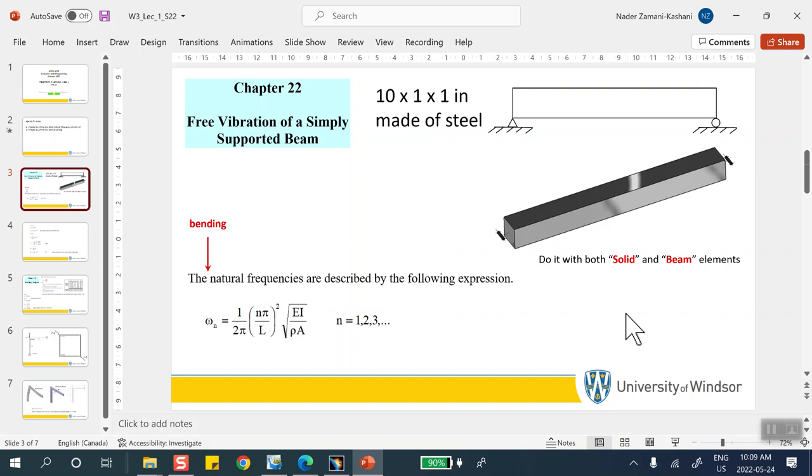this is a fact, avoid using planes of symmetry of the structure when you're doing natural frequency calculation. Because if you said this structure that I've drawn here up there has a plane of symmetry, I agree with you, like that.